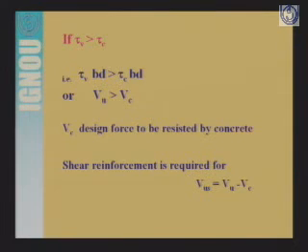Meaning the design shear force Vus we can determine by subtracting Vc from Vu. So we have to provide the shear reinforcement for the component of Vu which is over and above Vc, and that we denote as Vus.